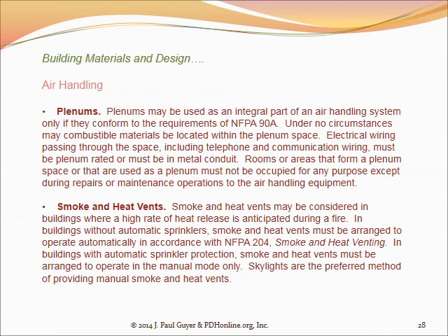And so you have to prevent that using automatic dampers, fire or smoke dampers that close automatically in the ductwork depending upon where the fire breaks out, and also through the use of fan controls, duct configuration, and dampers, switching the air conditioning, the HVAC system, from its normal function to that of an exhaust system to exhaust the smoke directly out of the building from the location where it's being generated within the building.